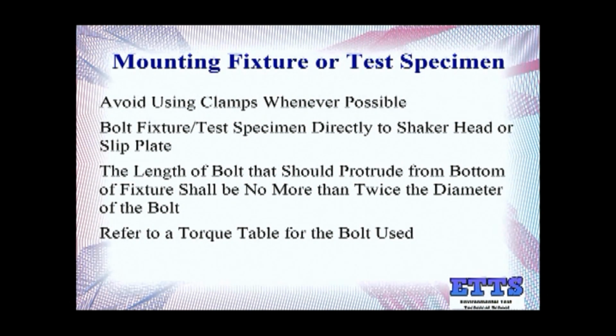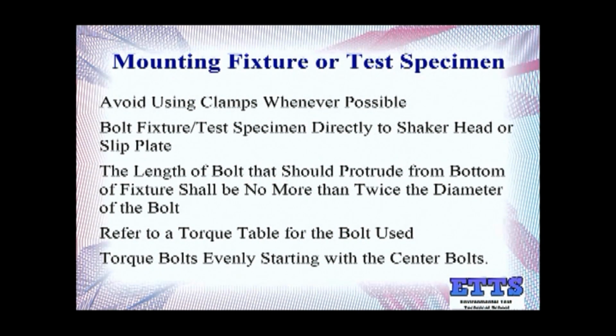Also, refer to a torque table for the bolt that you are using. Always refer to your company standard for a torque spec, or if they do not have it, look up a torque table online to ensure that you are torquing your bolts to the correct torque specification. Torque bolts evenly, starting with center bolts. You want to work in a star pattern, typically, starting with your center bolts and working your way out. This will ensure that the torque is evenly distributed throughout your entire fixture.